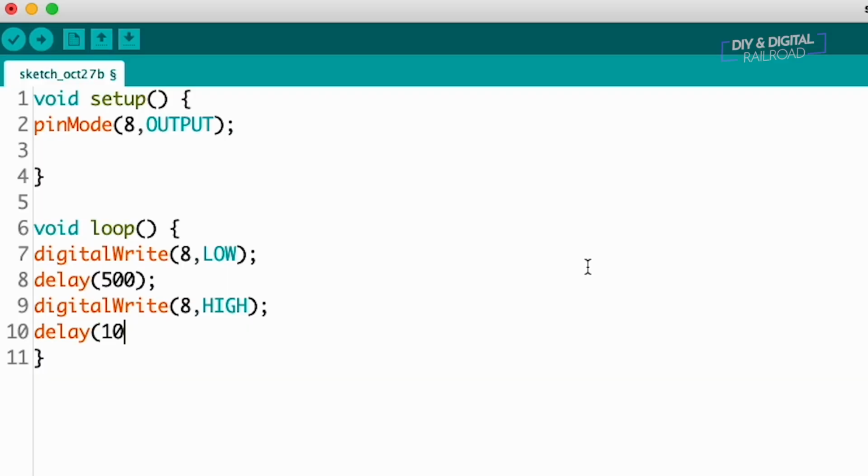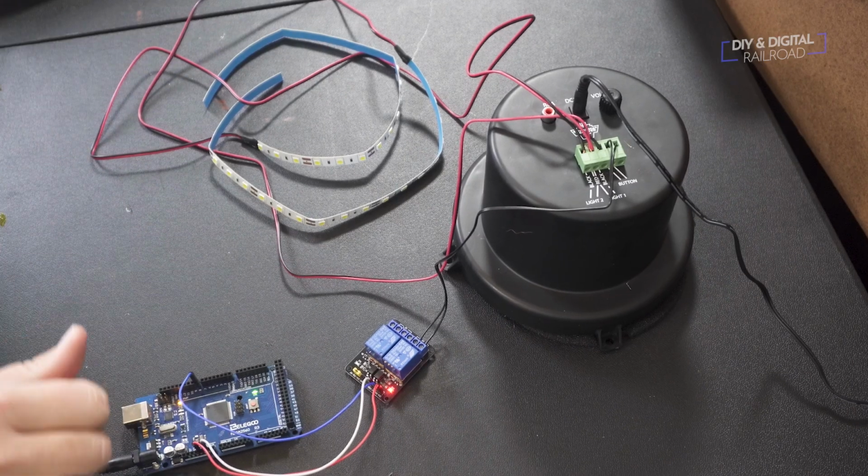Now we need a delay before the next button trigger. And we're just going to write delay(10000); which will give us a 10-second delay. And that is it. The low enables the connection that the button made and triggers the lightning storm. That goes on for a half second. Then we go back to high, which it holds for 10 seconds, which is like us not clicking the button. And then the whole thing restarts.